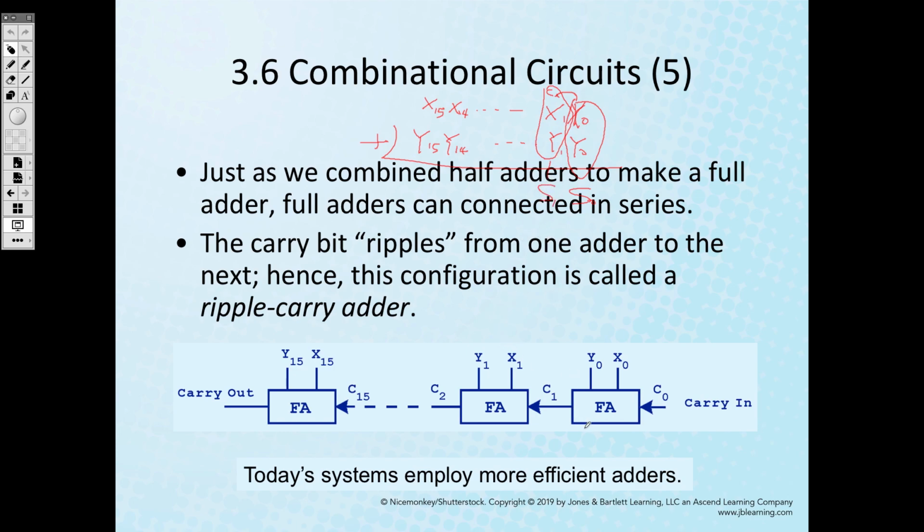So using the full adder, we can add multiple bits by cascading full adders, such that you add x and y at the least significant bit. The carry in should be 0, and then this bit produces a carry, passed to the next position, where you add x and y with the carry. It produces a carry and forwards it to the next position, and so on. So if you cascade the full adders this way, you can implement multiple bit binary numbers.